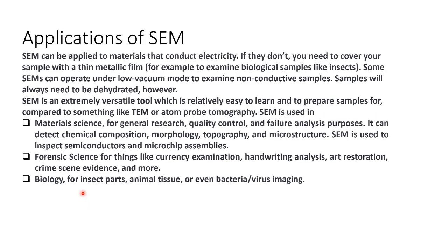So there are various applications for SEM. It can be used to check the conductivity of a material. If a material is not conductive, we have to apply a very thin metallic film of carbon, gold, silver, or sometimes platinum. Platinum, gold and carbon are normally used for coating the sample.